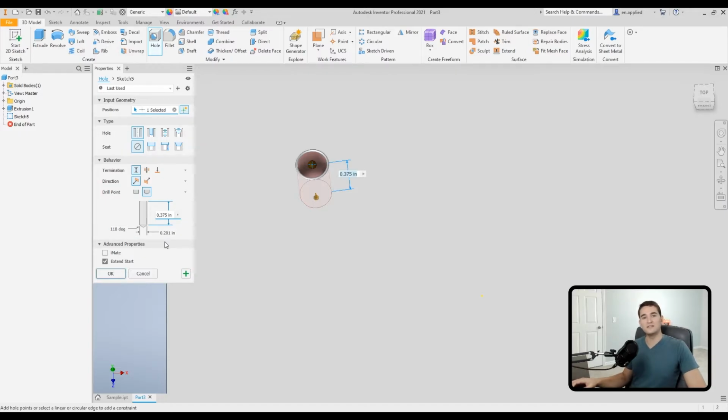it's a good idea to leave that because it gives you a good visualization of what material is actually left in that space. Because if you're drilling into a thin part, you need to know how much material is between the tip of that cut and the other side of your part. So that's just my opinion on the matter. Again, it really doesn't matter, just as long as you're always accounting for those things towards the end product. So that's that option as well.